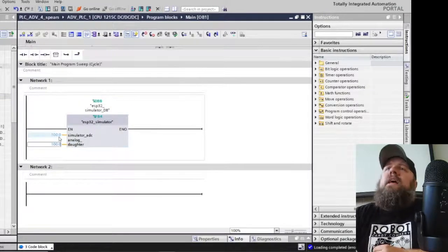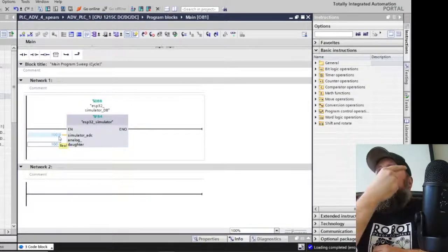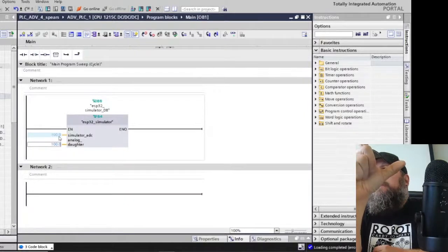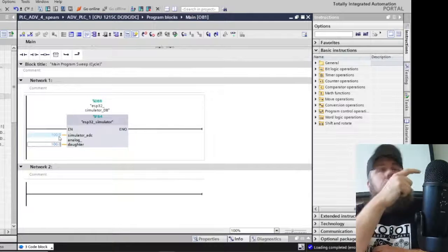But the reason that's showing up right there is because it's got the right resistors. You need a 500 ohm resistor to get from 20 milliamps to 10 volts. So that's what those three resistors are.